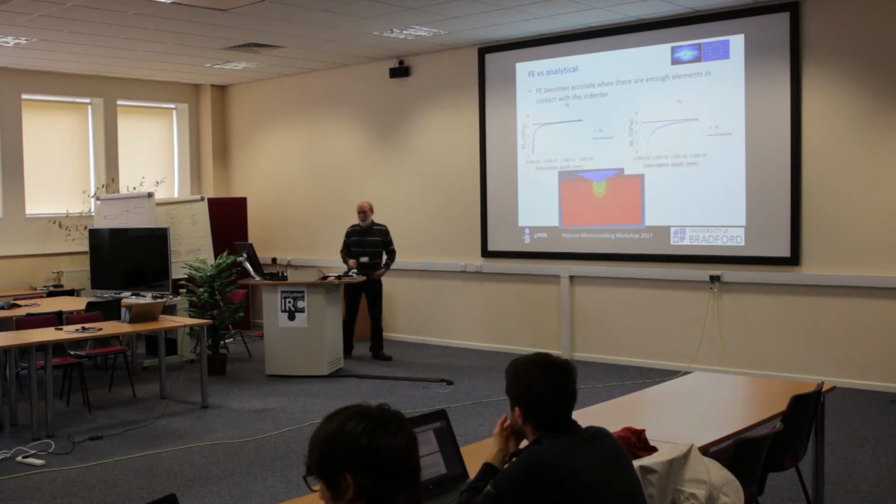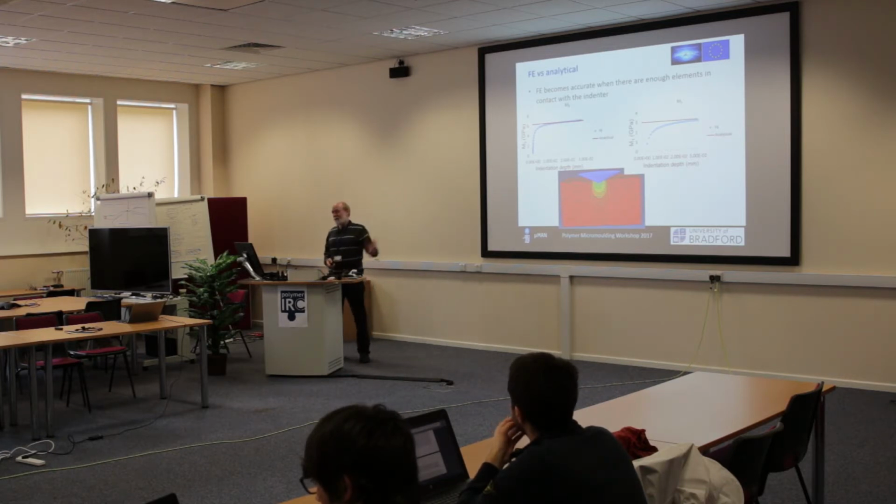And it doesn't matter if it's an elastic system. Just need to push it in far enough so that I'll get reasonable contact. Of course, the stresses are huge because it's elastic. There's no plasticity on. Again, that doesn't matter. So M3, we seem to have nailed it. So that was the simpler of the two analyses.